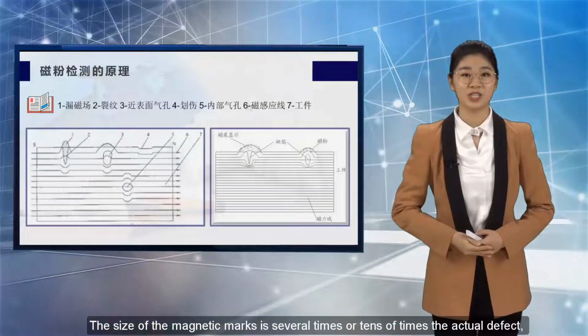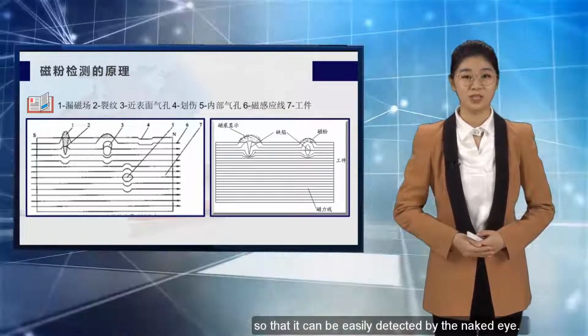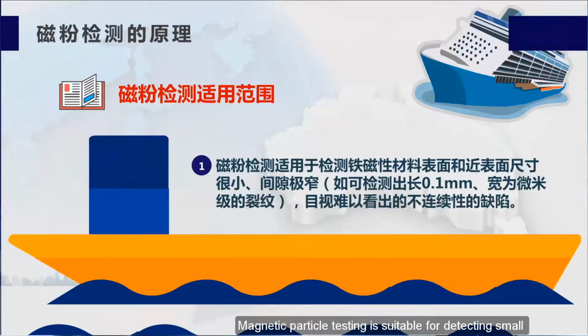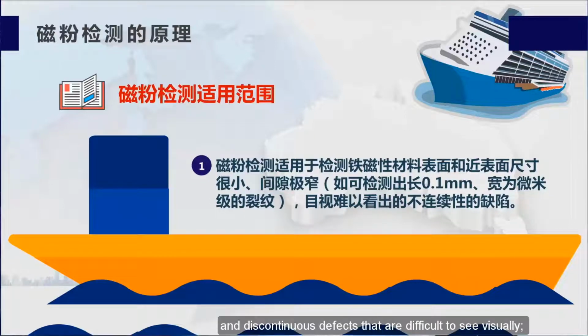The size of the magnetic marks is several times or tens of times the actual defect, so that it can be easily detected by the naked eye. Magnetic particle testing is suitable for detecting small and narrow gaps on the surface and near surface of ferromagnetic materials. For example, it can detect cracks with a length of 0.1 mm and a width of micrometers, and discontinuous defects that are difficult to see visually.